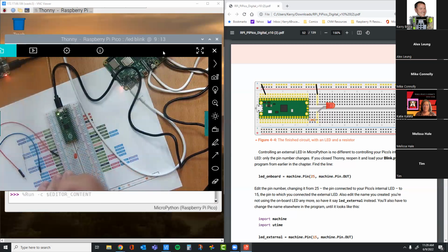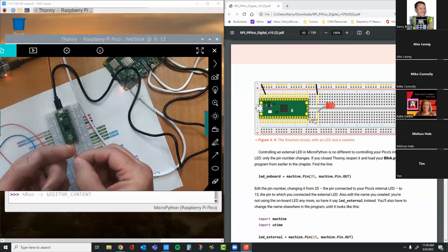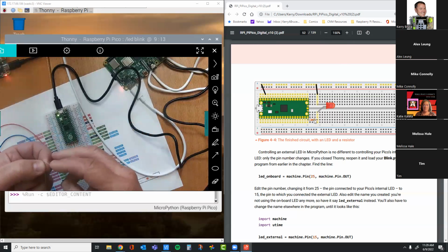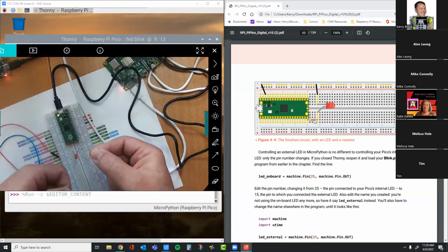So these are seated into these ports on the breadboard, and I've pushed all the way down so that it's solid on the bottom. Okay. Now, according to the diagram, right over here on the long leg side, I'm going to insert a resistor. So I've got my resistor here. I take my resistor and I'm going to bend the wires so that I have the U shape there.